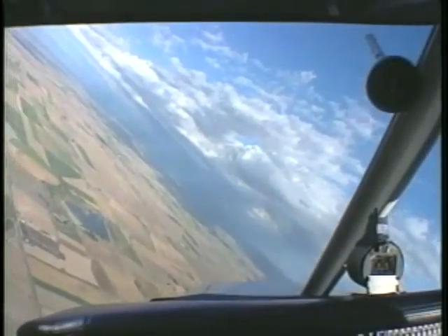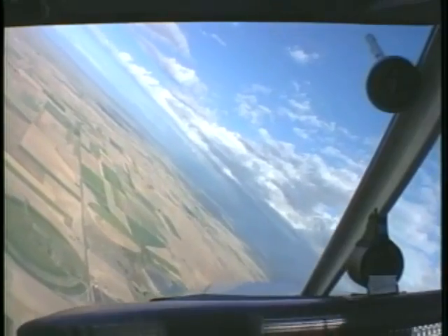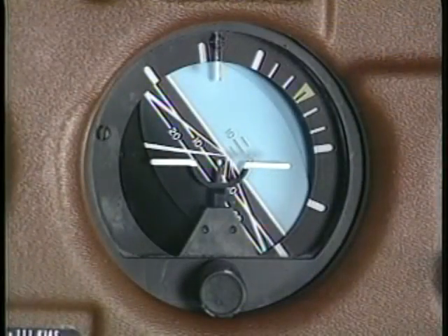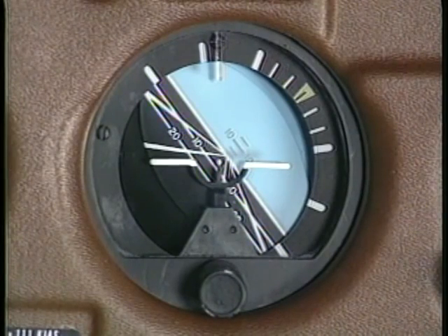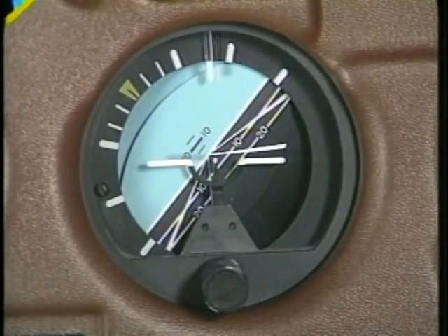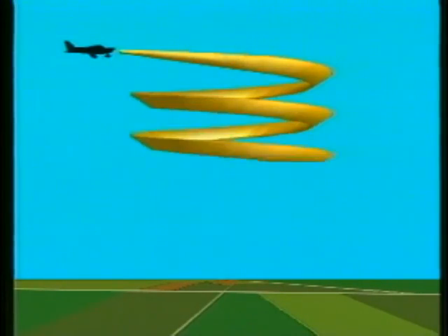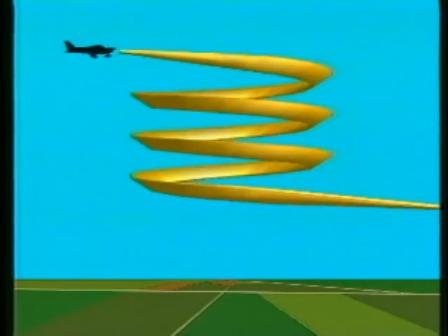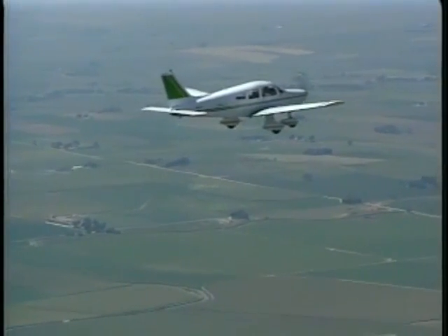A steep spiral is basically a gliding descent using no more than 50 to 55 degrees of bank where you maintain a uniform radius around a reference point. The maneuver can be performed either to the left or right. Typically, you'll enter the procedure, complete 3 360-degree turns, then roll out on your entry heading. Let's look at how you perform the steep spiral.